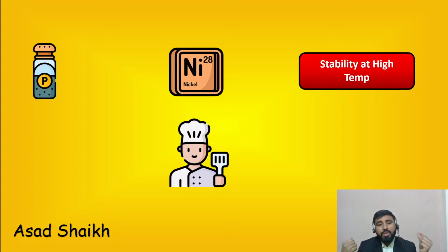If the corrosion allowance is low, yes, you can go ahead with the same material. Standards like the API standards don't have any specific clause, or at least I have not come across any clause, which talks about corrosion allowance in valve walls. So whatever thickness we assume, in that case I would tell you to please be very cautious if the corrosion allowance is high.